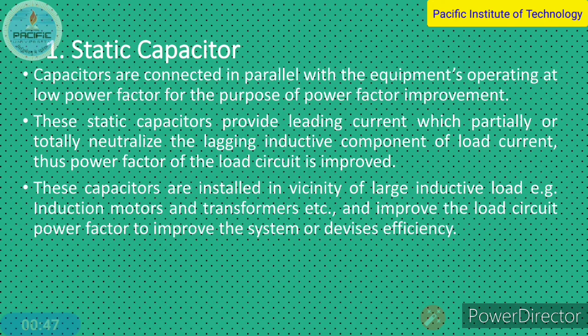Static capacitors are connected in parallel with the equipment operating at low power factor for the purpose of power factor improvement. They are connected across motors, arc discharge lamps, induction welding and induction heating equipment. These are the equipment which draw a heavy amount of inductive reactive power, and for this, the capacitor is connected across the devices.